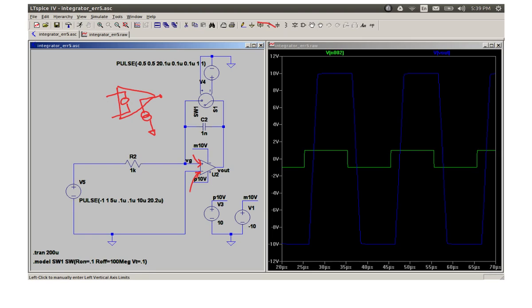However, even the universal op amp has some finite gain, and if you have a finite gain, it's getting closer to a realistic op amp, then the plus and the minus signs do matter. So the plus means if you have a small voltage delta V here, then this delta V is getting multiplied by a gain A and coming out from the plus to the minus. And this can either aid the way the input is coming, or it is either positive or negative feedback.